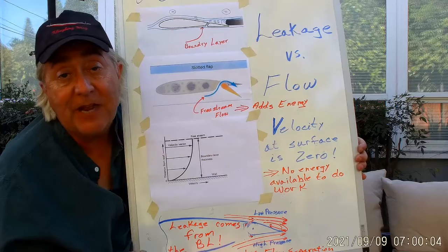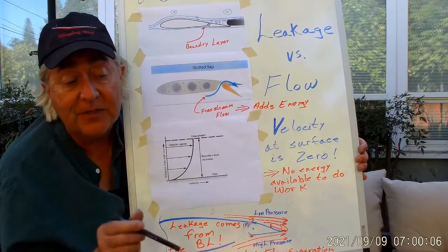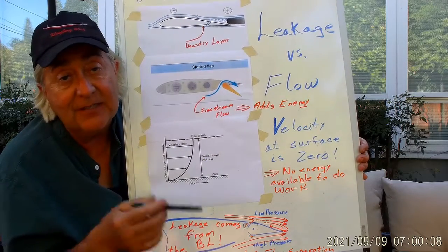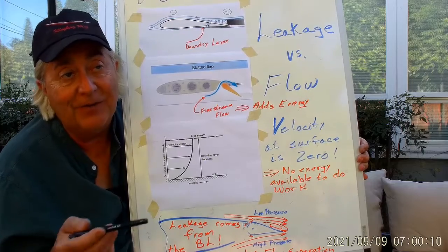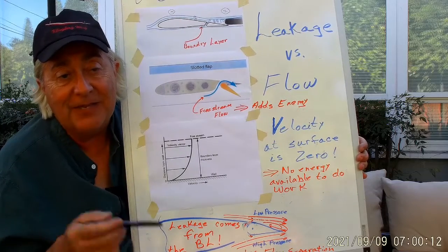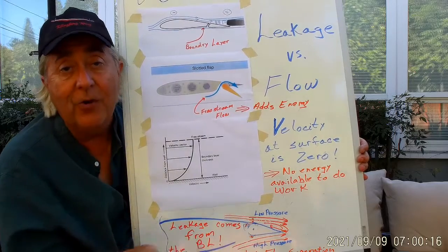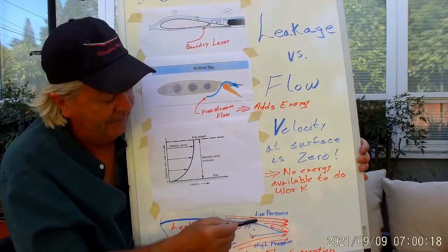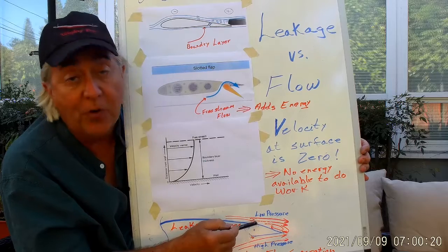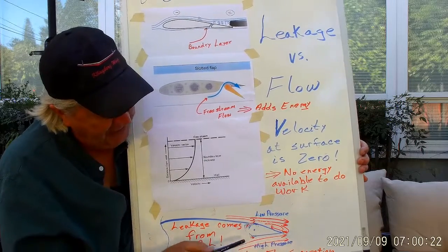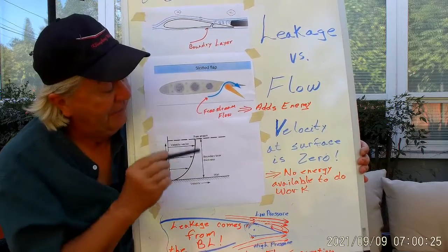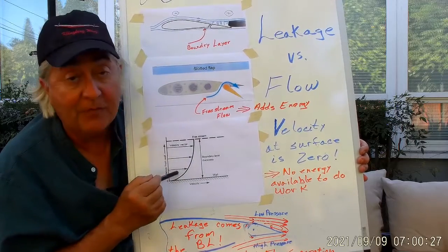The other problem that I was having was we're down at low Reynolds numbers because we're essentially standing still. The wind's only blowing 9 miles an hour. Reynolds number's about 500,000. That's right in the bad zone, and it's very easy to separate the flow back here. In normal flight, it'll be up around 1 million, and the flow will be much more amenable to staying attached here. So that's the difference. Free stream versus peeling off the boundary layer.